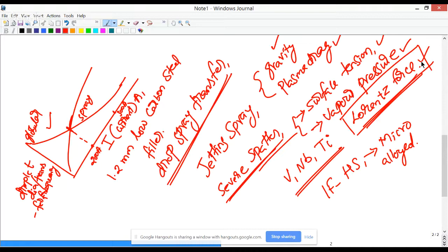So that's why in aluminum containing TRIP steels, we also have to have some other alloying additions to achieve the strength level equal to the silicon based TRIP steels, which I already discussed in detail. Sometimes we also add phosphorus, because phosphorus also does the job by increasing the strength due to solid solution strengthening, and suppressing the cementite formation. But we looked in detail at the role of phosphorus, how it embrittles the weld.